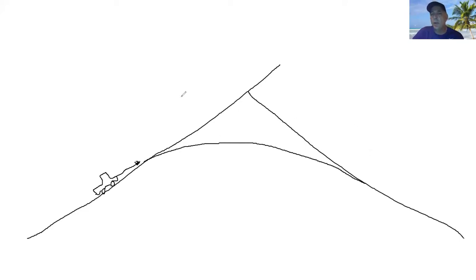This is what we call a vertical curve. There are some key components of the vertical curve. One, there's a particular grade going into the curve. This is going to be symbolized by what we call G1, which is the grade going into the curve. And then there's G2 over here, which is the grade going out of the curve. So we'll be talking about those as we go in.